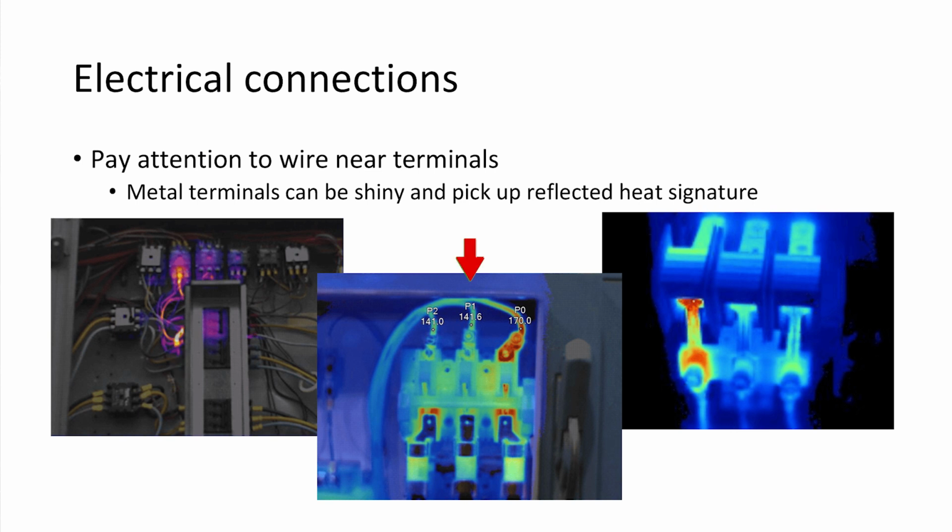But if I look at this thermal image, would any of you say that these are problems? Yes. Okay. Would you say that this is a problem? Yes. Now, I'm going to say that these down here may or may not be a problem. We don't know because I don't know how or the area that this image was taken in. This is definitely a problem because I've got heat extending down a wire. This is affecting the insulation, which means it's going to be affecting the composition of actually the copper in the wire or whatever it's made out of, if it's aluminum, whatever. These, maybe, maybe not.